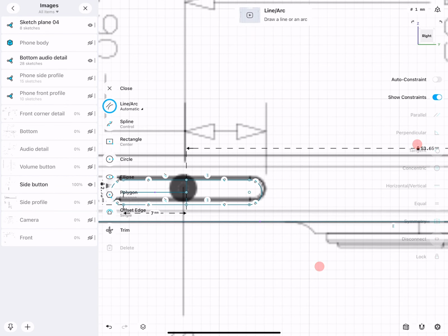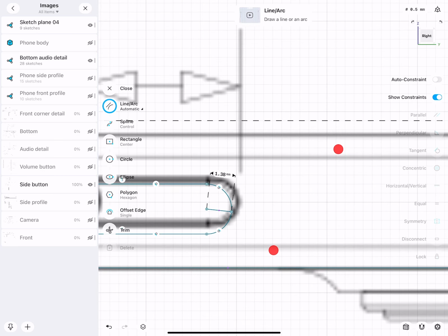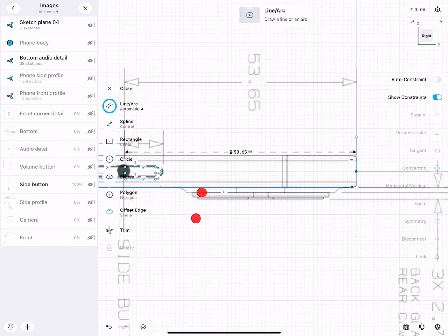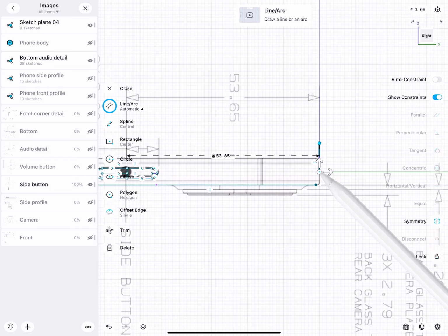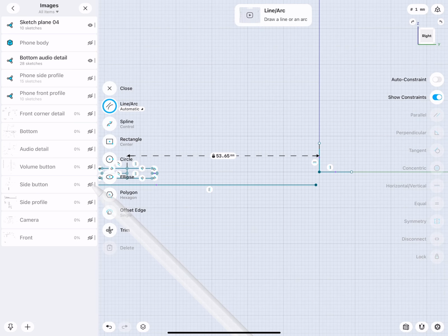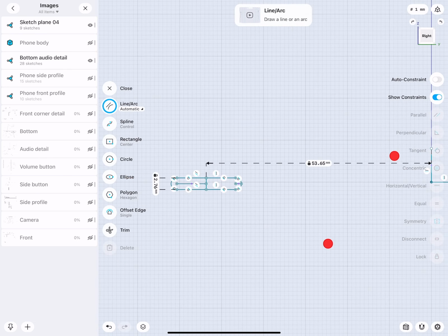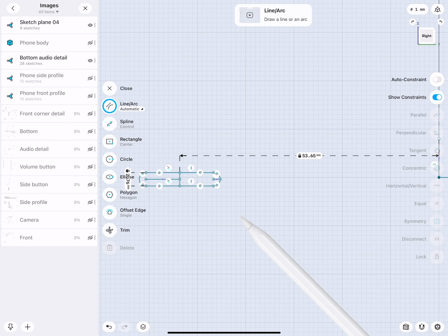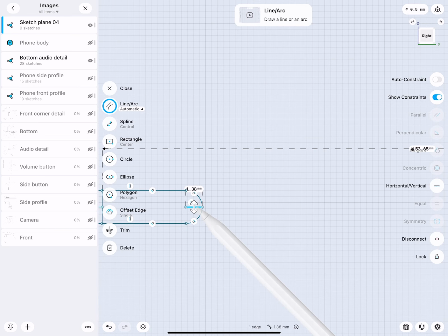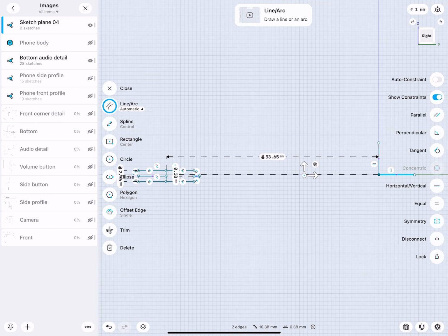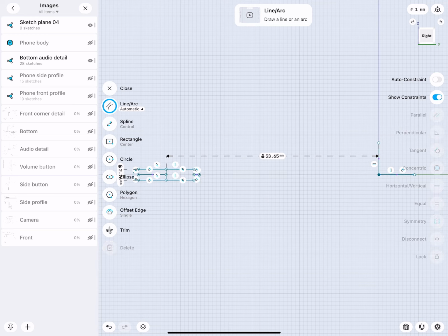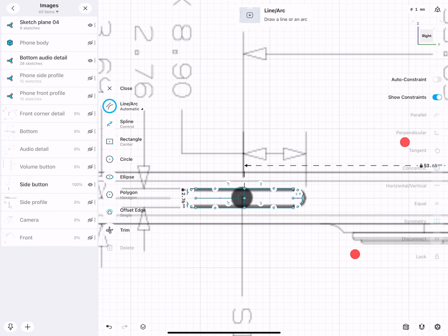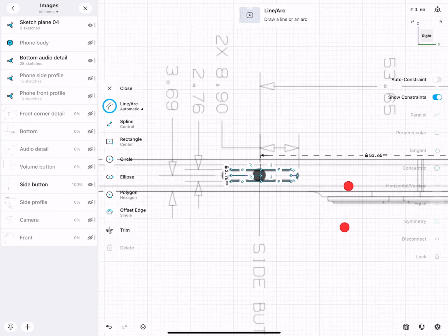So what I will do is simply the following. I will draw a line here. This line I will make horizontal, and here is actually our world center. So this I will lock. This actually I will remove now, because this is for also the glasses. That's even above the phone body we modeled. So then this line and this line, please be tangent, and that moves it up. Now let's see if this actually lined up. Yeah, there you see, perfectly it does. Very good.